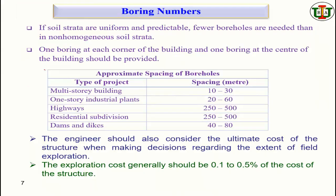Okay, so actually this is the last slide. I'll take 1 or 2 minutes on it. So, number of borings you need. This is a very common question, sir: how many borings do I do in a project, or how many boreholes do I need to consider for soil test, right? So there are some guidelines, but these are not fixed. You can increase or decrease based on it. But if you have uniform soil, you can follow this guideline.